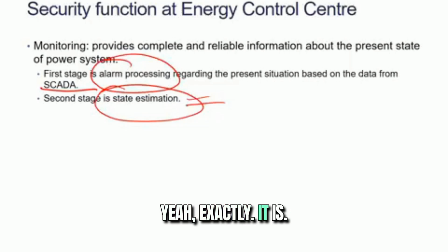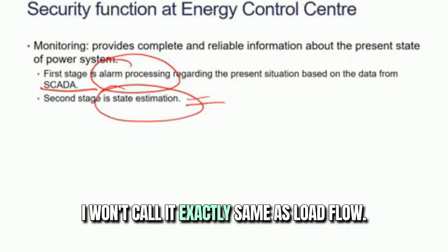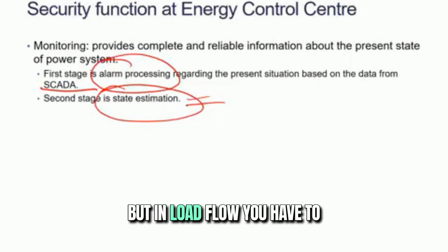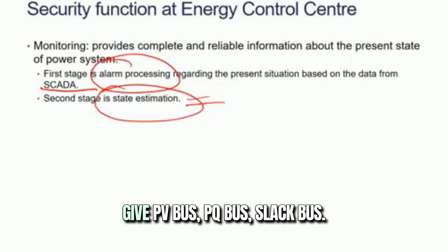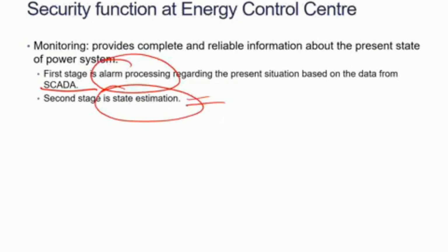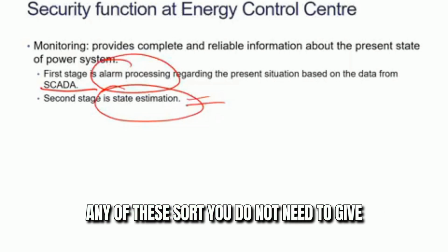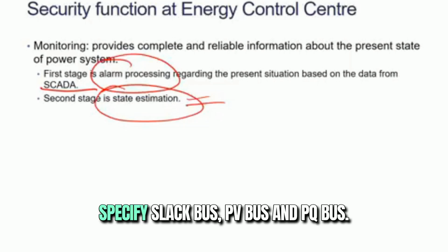Perfect. Yeah, exactly. It is equivalent. I won't call it exactly the same as load flow. It is equivalent to load flow. But in load flow, you have to give PV bus, PQ bus, slack bus. But in state estimation, you do not have to give any of these sort. You do not need to specify slack bus, PV bus, and PQ bus.